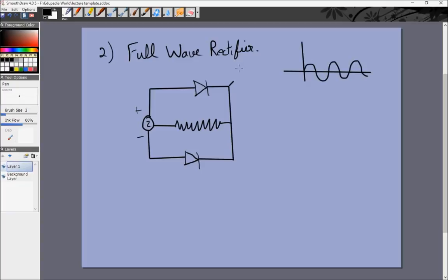So during this half cycle, this is negative and this is positive, and this junction is forward biased, whereas this junction is reverse biased. Because this is negative, we'll assume this to be 0 potential. If this is positive, this is forward biased and this is reverse biased. So current will flow in this direction, and since this is reverse biased, no current will flow here. So all the current flowing through this wire will come out through this resistance. So there will be a current through this resistance.